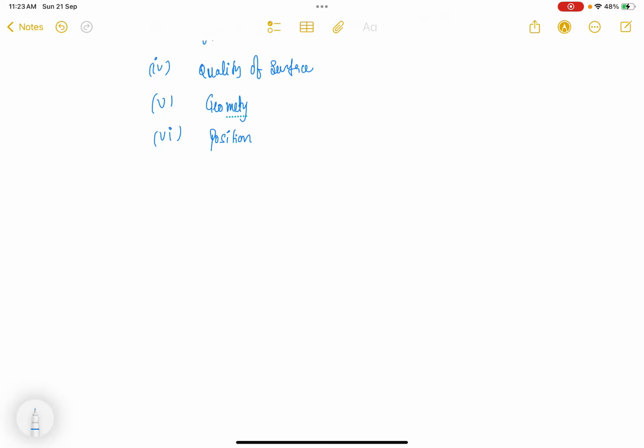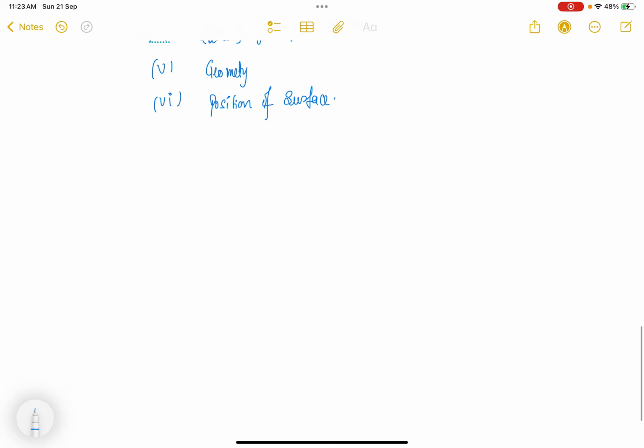The flat plate is horizontal or vertical or inclined, depends on it. h is generally an experimentally determined coefficient, and one thing to note is that h is not a property of a fluid.